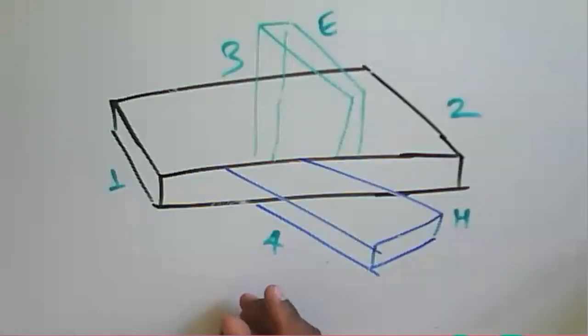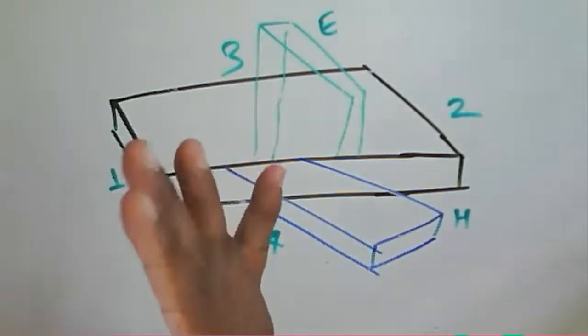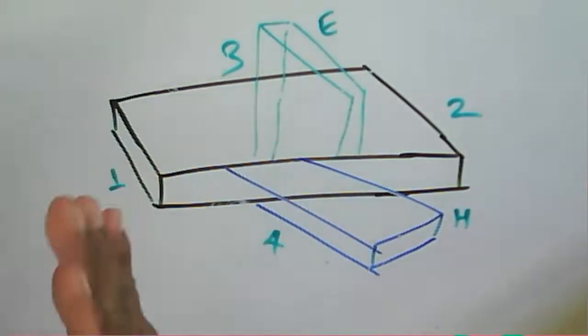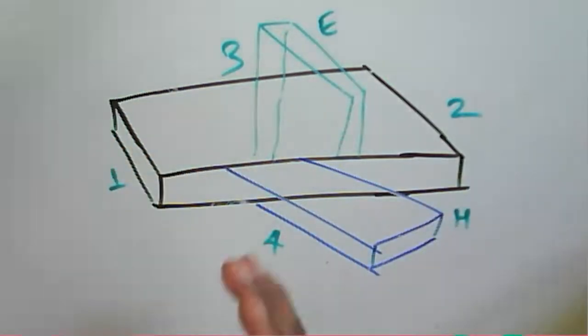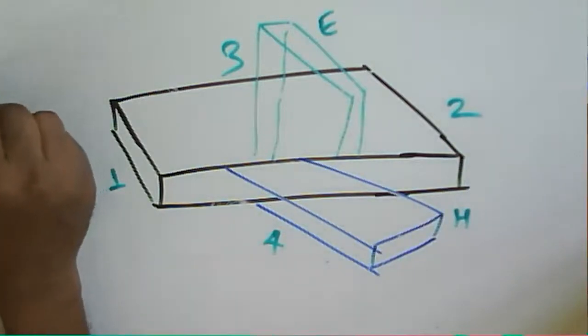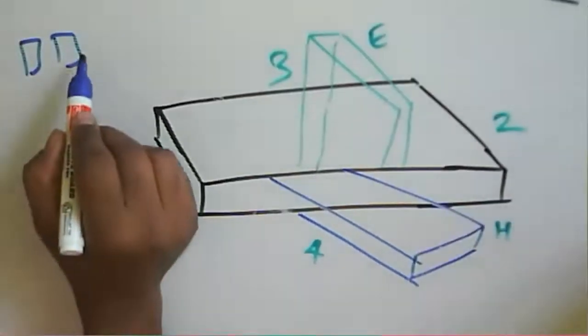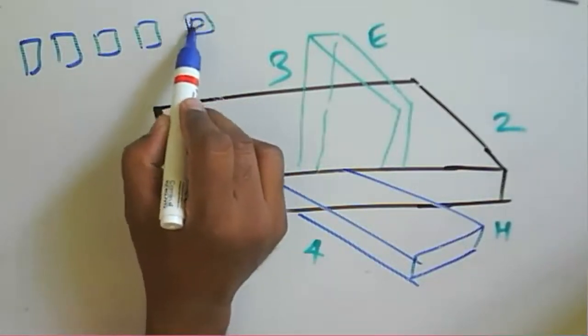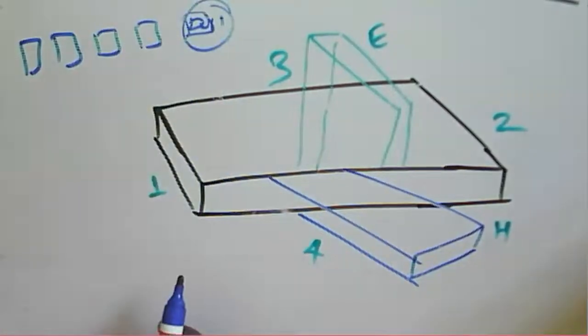so that's why it's called a magic T. To measure this, if we don't have a network analyzer, then how do we measure the S parameter of the given T? For that purpose, we use a microwave bench setup. We connect a source, then isolator, then attenuator, one component after another, then the slotted section probe carriage, and then the device under test. That device under test is the magic T.